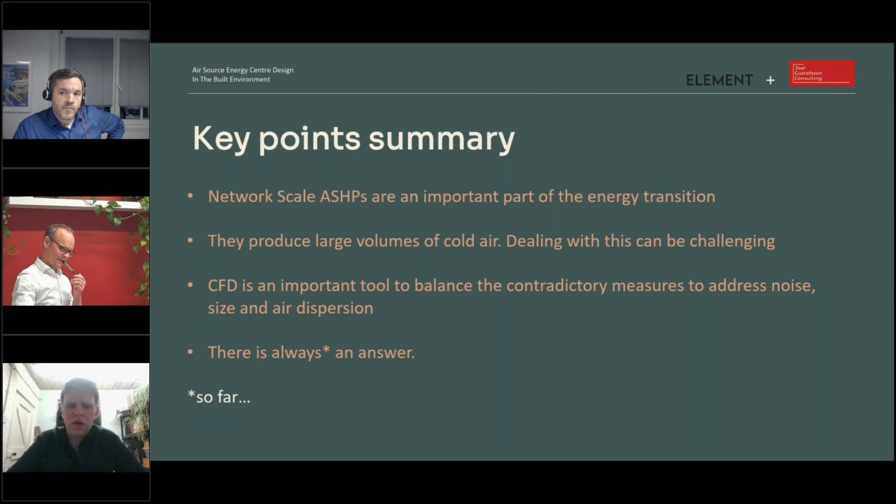There are a few projects we've worked on in the past where the iterations have been landscape, and that was quite a tricky process, because the failures weren't coming from the expectations of what should be happening with the air, but actually from the stability of the geometric modelling and then the meshing. So that was quite a challenge that we had to consistently iterate, that landscape. That was taking days. But typically speaking, within an hour, I can get an answer.